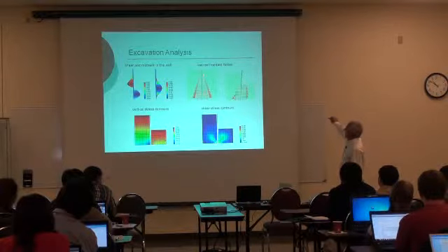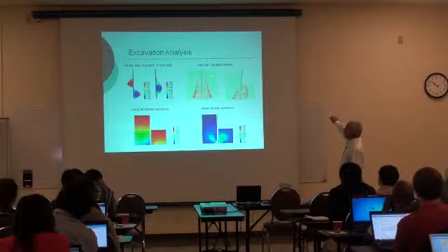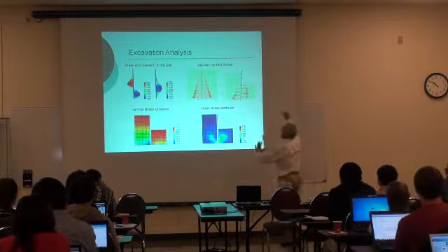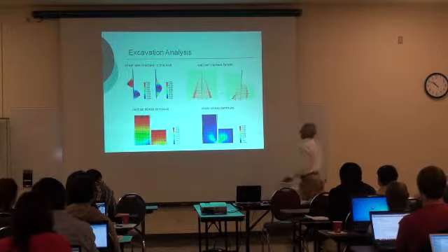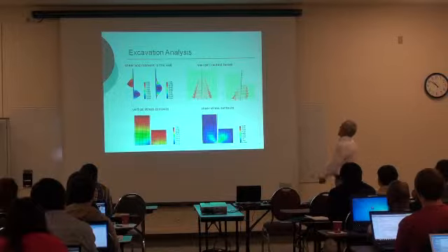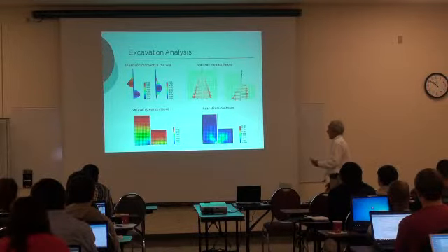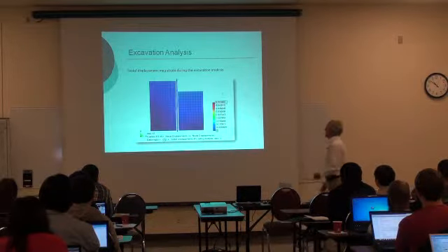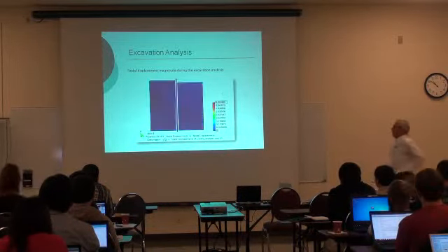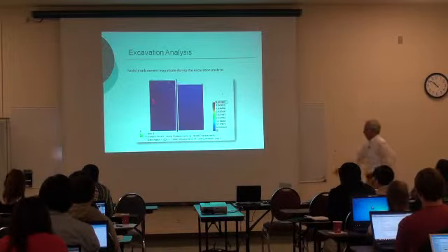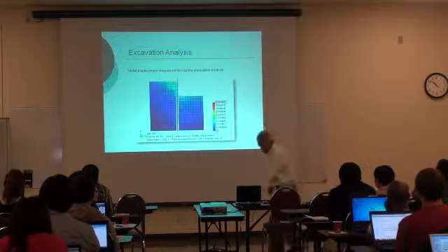This is the initial contact forces before you remove the elements. As you remove the elements, you see how these contact forces change. And again, you can make plots of vertical stresses or horizontal stresses or shear stresses. And you can create also animations. So this is an animation of the deformations that happen as you remove the soil elements. And again, the contours are for deformation here.